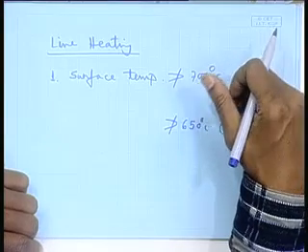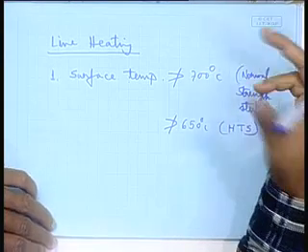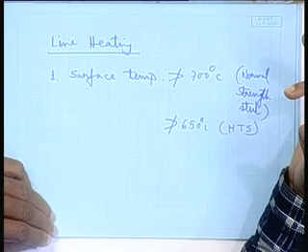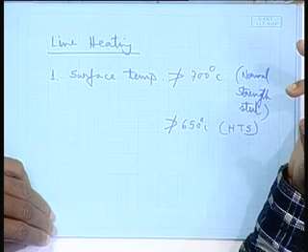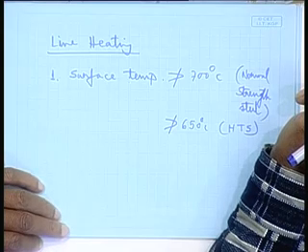If I could increase the temperature, my process of bending would probably be more effective, but if I increase this, there is another side effect, because 723 degrees is the recrystallization temperature, meaning a microstructural change would take place. So the plate property would be adversely affected. So there is a limit on the temperature of the surface.